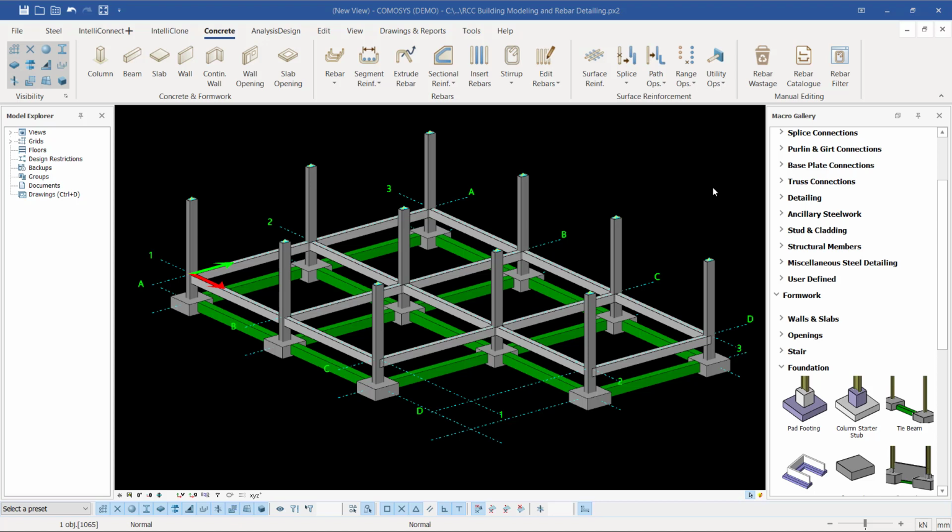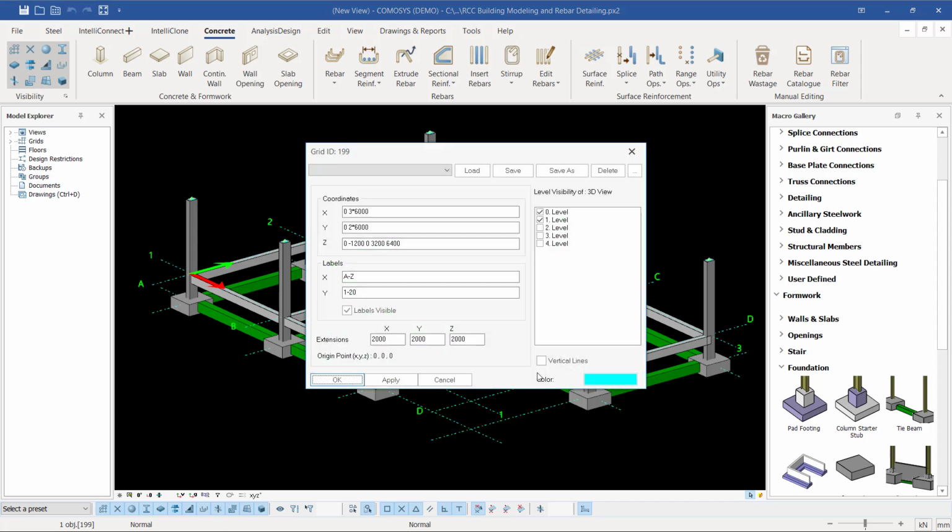This is part 3. On this step, I'm going to show you how we can add the beams, or more beams, in accordance with the height of our building, as I had described or defined when we were creating the grid lines. If I double click on the grid line, you can see the heights we have. From zero level, we stretch to 3.2 and to 6.5.